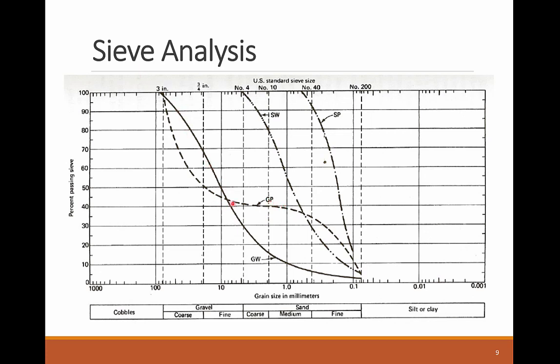Well-graded gravel, on the other hand, provides better strength performance as the different sizes of grains, as you see here, smooth transition, provide better interlocking and stability between the grains.